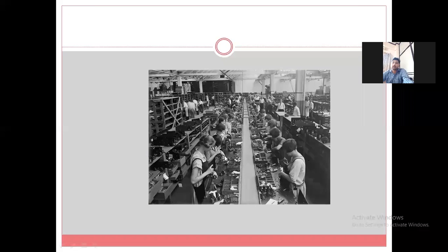Production time loss. So for that purpose you need to ensure that the process or the task should be assigned in such a manner, or the assembly of a product will be segregated in such a manner, so that the time required will be constant for each workstation. And if it is not possible to provide a constant time, in that case you should ensure that multiple similar kinds of workstations should be provided for that particular extra time required task.